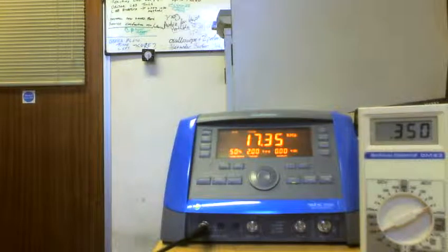And that's why I don't particularly like using them, because you haven't really got that wide range. So if you're testing a filter or anything like that, probing data lines and things like that in a circuit, or you're trying to build a clock or anything like that, you can't use the multimeter for that. It's completely useless for measuring those sort of values.